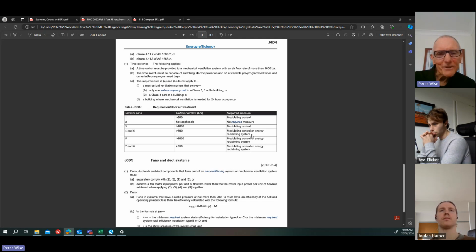Well, you haven't done it, so I'll tell you what the obvious question probably would be. What if you have a whole bunch of fan coil units in a space and you've got a common outside air system which delivers more than 500 litres a second, but it's distributed to all those fan coil units? So each one might be getting, let's say, 50 litres a second or something like that. Do we have to have an ERV?